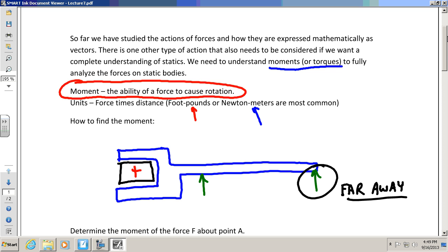And if they didn't break, you know how heavy they would be? Oh my gosh. They'd have to be really heavy. It'd have to be a big honking wrench that's super heavy in order to hold that kind of force such that you could turn something. But you'll notice, if you need a big industrial application to turn something, the wrenches get bigger. And not just thicker, they get longer, because the longer the wrench, the more torque you're going to get.